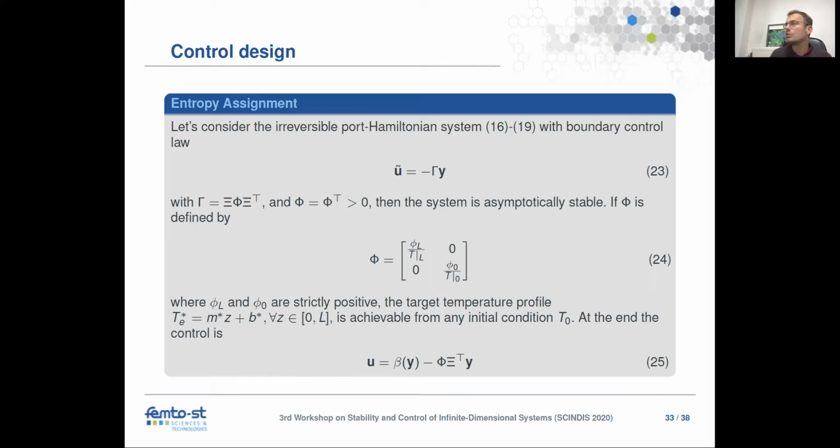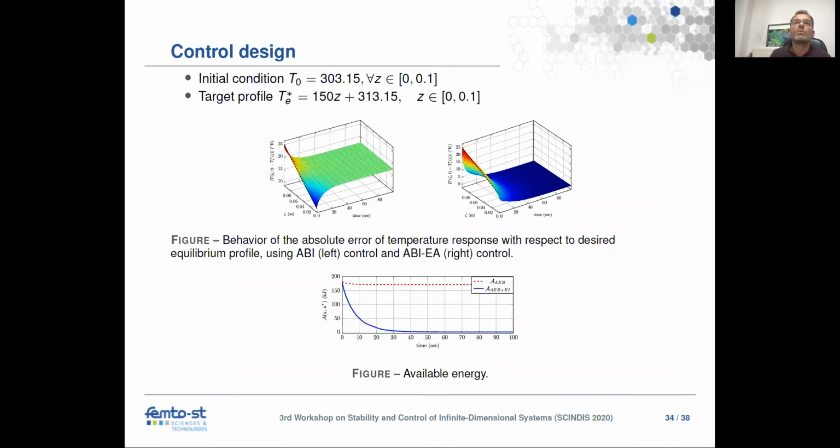In the linear case, it leads to very simple control design laws, but you could think about more complex laws for nonlinear systems. Of course, if you want to prove stability, then you have to prove the existence of solution, pre-compactness of trajectories, in order to be able to use LaSalle's invariance principle or some convergence arguments in order to show, properly, that you reach exactly the equilibrium. But you have Lyapunov arguments that give you that if you have existence of solution, it reaches the equilibrium position. Okay, and we did apply it to the very simple example I mentioned.